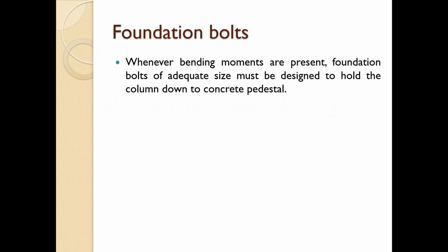Before moving to the gusseted base, you'll see a small part of this foundation, that is the foundation bolt. We provide the foundation bolt at least nominally, because sometimes due to some reversal of stresses or due to some tension, there might be tensile forces in the foundation, so that the column will move or lift from the foundation. So to keep the column in position, we provide the foundation bolts.